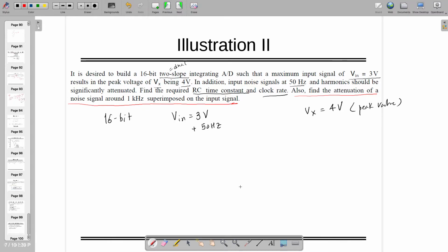In SMPC, switch mode power conversion, we are operating that. SMPC or SMPS? SMPS is the power supply; conversion, we say SMPC. So we are increasing the switching frequency to reduce the size of that SMPC because of the L and C. Because if inherently this ripple would be large, then we'll have to provide more capacitance at the output to compensate that.